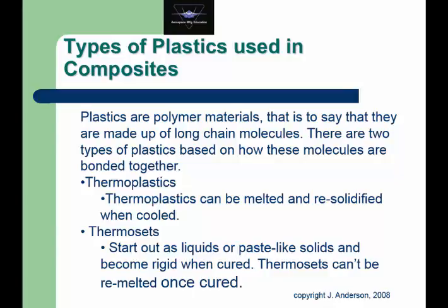So what happens there is that once this thermoset solidifies, once you form that cross-link, you can't remelt it. As you raise the temperature, you can't break those chemical bonds between the chains, or when you do, you're breaking the backbone of the chains at the same time. So typically you end up charring a thermoset rather than melting it.